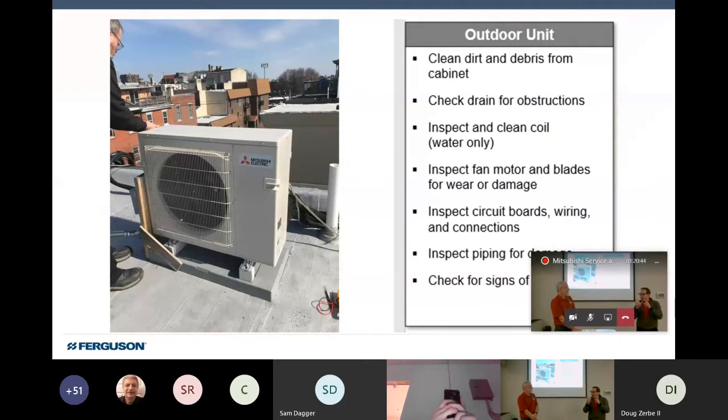What we realized, when we put the maintenance tool on it, which is another class that we offer, and using that maintenance tool, we were able to see that refrigerant leaving the unit was, let's say, 45 degrees. By the time it got to the indoor head, it was 10 degrees warmer. How about that, right? What we found out was that the lines that had come out horizontally, drooped down, ran around the house, and then went up the pipe. Well, that whole long 10 feet was filled with water from where the pipe had been condensating. Inside the insulation.